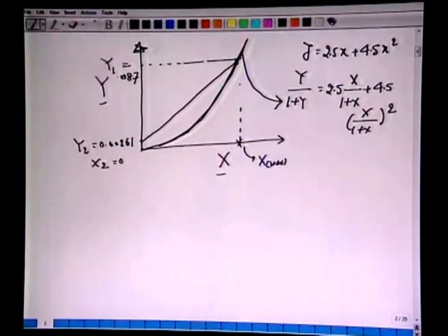All right. So this is the maximum. We have L by GS. So this will give you the highest concentration we can have in the spent liquor, corresponding to this minimum LS by GS flow rate. Okay. So this X max from the graph, if you plot it, this will turn out to be around 0.31.